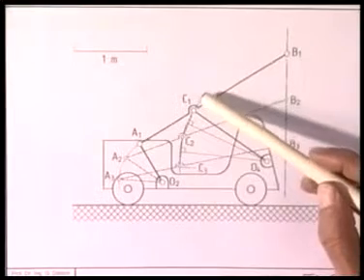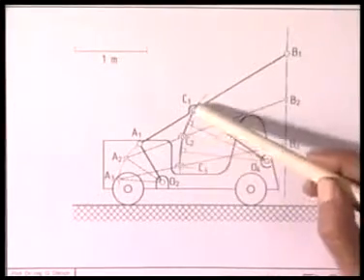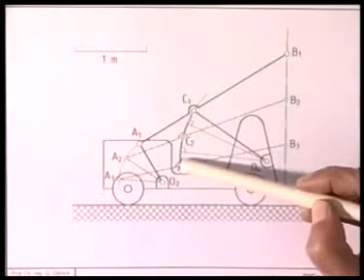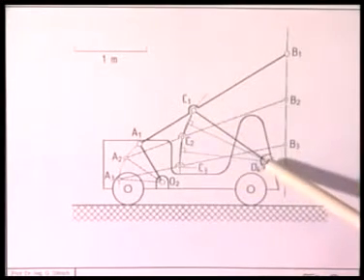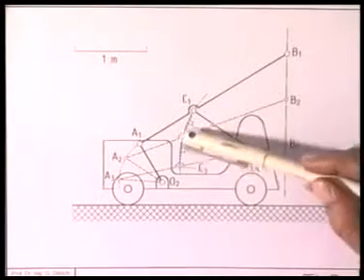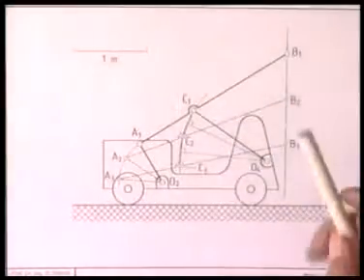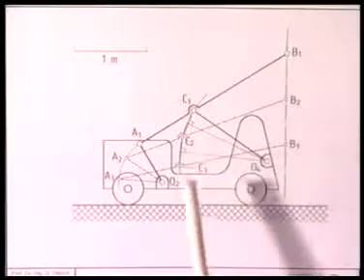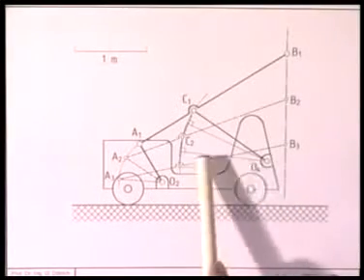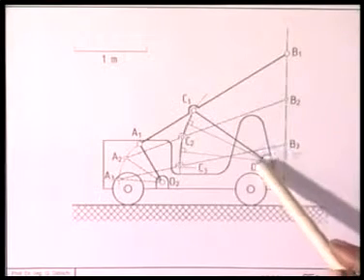Then I can always draw a circle through these 3 points, namely C1, C2, C3, and the center of this circle is at O4. The center can be easily determined by drawing the mid-normal of C1, C2, which is this line, and the mid-normal of C2, C3, which is this line, and these two lines intersect at O4,